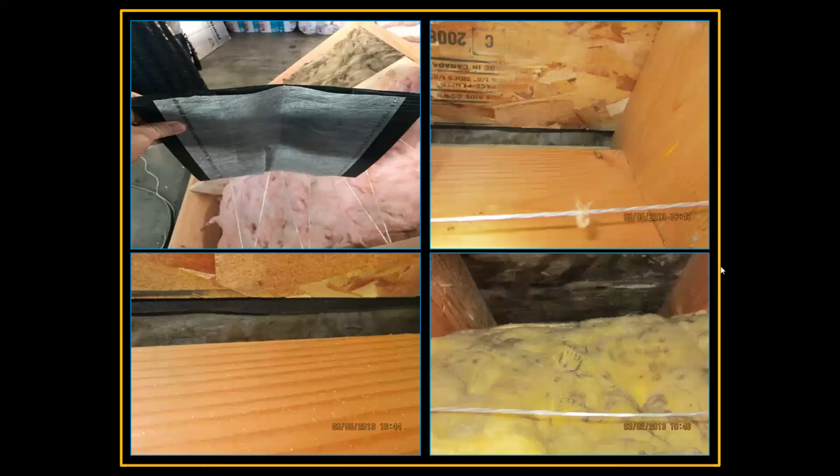This is the same place. So one of the problems that we have with ridge vents is a lot of them today still have this filter fabric on them. The problem with the filter fabric is when convection gets going the way it's supposed to and up through the underside of the sheathing, it carries dust particles and everything else. You can see in the upper right here, you can see how clogged this gets. So either use ridge vents that do not have this, or if this is on the ridge vent, I would take this off.